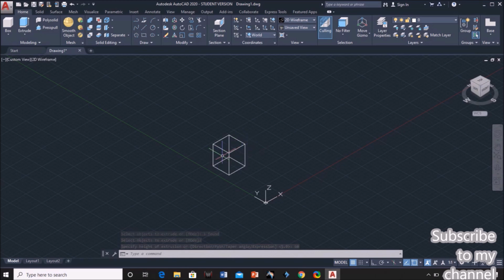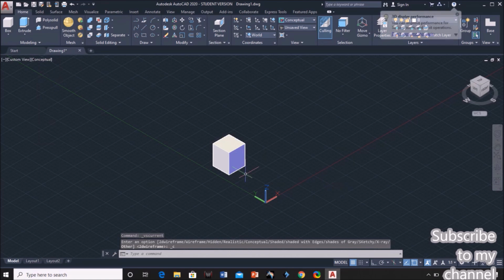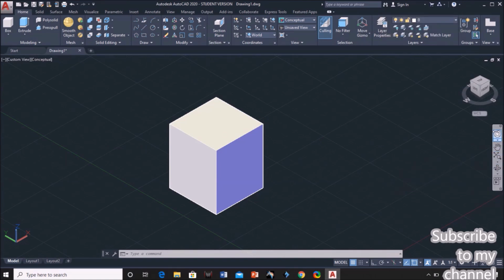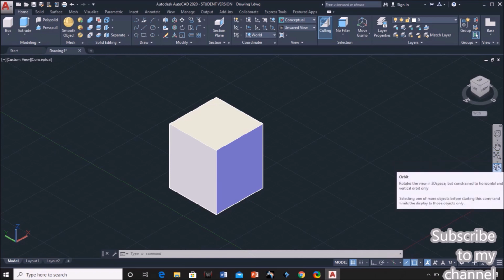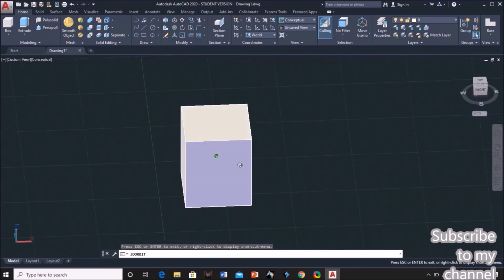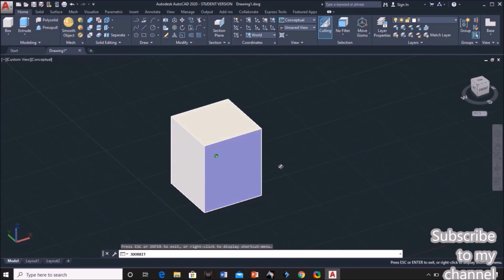To get the object in 3D, go to visual styles and check any one of these options to see the object in the different visual styles of 3D. So click on conceptual. Now the object can be seen as a 3D object. To see the object in 360 degrees, you can use these display commands. I want to rotate, that is orbit. So click on orbit and move the object, or we can rotate the object in any direction. So this is how we can orbit the 3D object in 360 degrees.